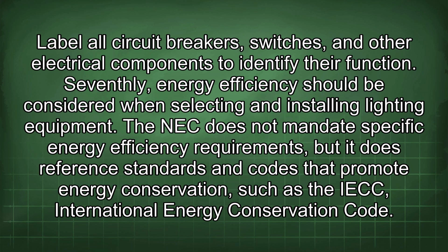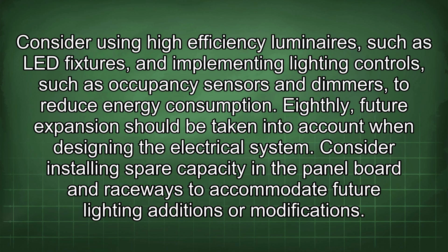Seventhly, energy efficiency should be considered when selecting and installing lighting equipment. The NEC does not mandate specific energy efficiency requirements, but it does reference standards and codes that promote energy conservation, such as the International Energy Conservation Code. Consider using high-efficiency luminaires, such as LED fixtures, and implementing lighting controls, such as occupancy sensors and dimmers, to reduce energy consumption.